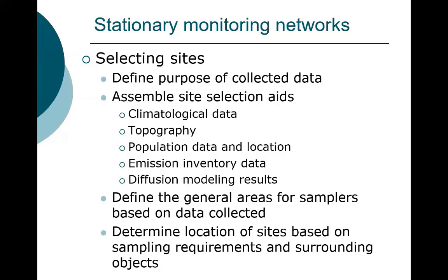If you're looking at an industrial source, then you're going to look at the emission inventory data. For instance, if you wanted to know what the SO2 levels or the NOx levels were from the MSU power plant, you could obtain the emission inventory data. They have sampling locations in the stack. They're continuously monitoring. And once a year, they bring in an outside firm to do the QA, to check all of the devices, to ensure that the values they're getting are accurate and precise.